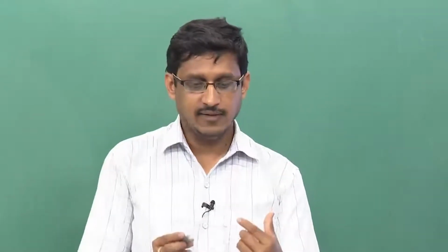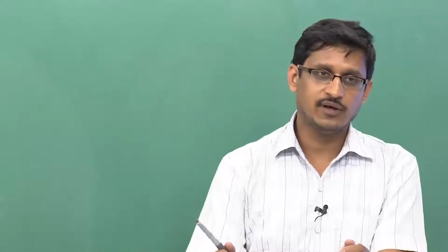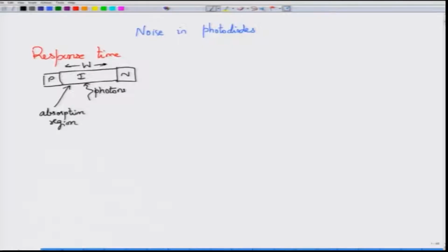Now, when and how do these electrons or holes actually propagate? They propagate under the influence of the applied electric field. When the electric field is applied, the charge carriers drift, which is just a way in which currents are generated. This drift velocity acquired by the electrons or the holes is proportional to the applied electric field, which is the result of the reverse biasing of the photodiode.